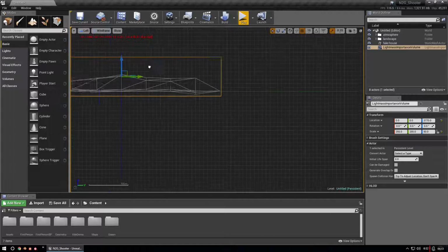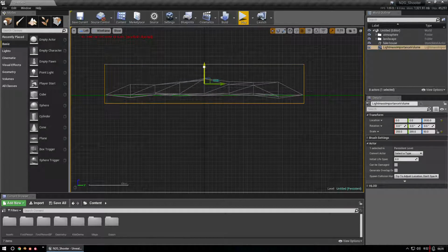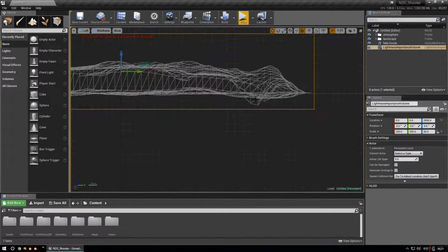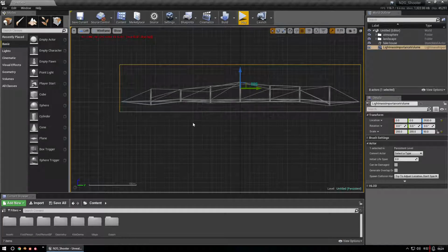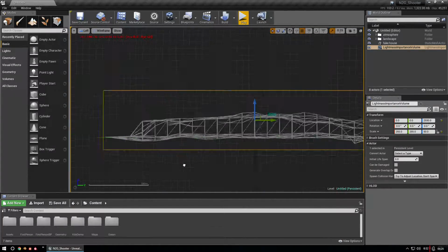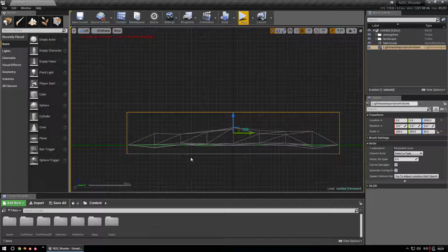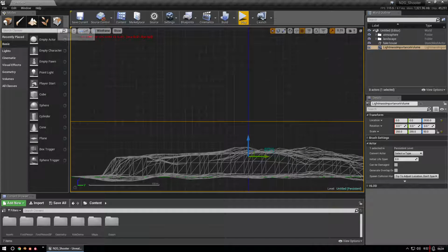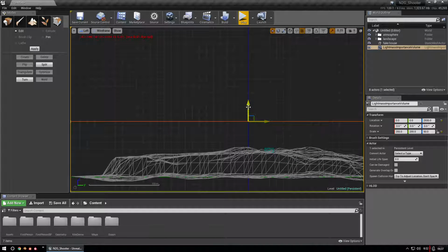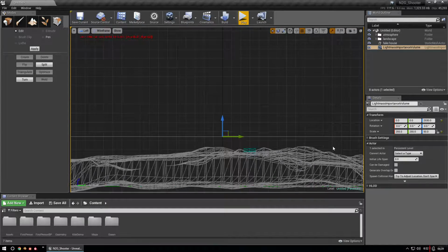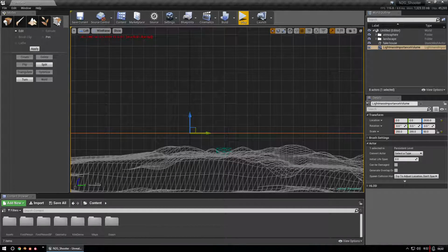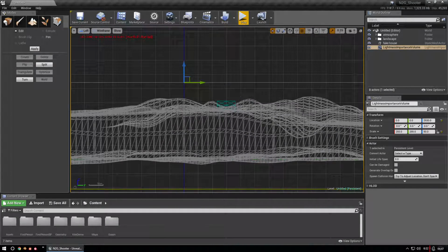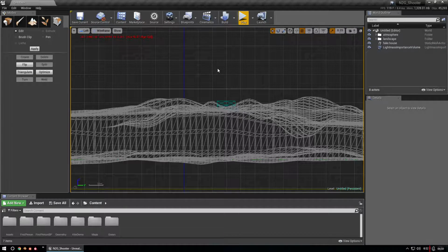I have to make sure that this little bounding box, this volume for my lightmass, tells the engine what is actually important when it comes to the lighting. So it's not throwing photons all across this whole grid area. It kind of speeds up the process. And max height hits here. So let me cheat a little bit. Just going that way. We're in editing mode, so it allows me to do these little cheap things here. Quick and easy. Bring that down a little bit more.